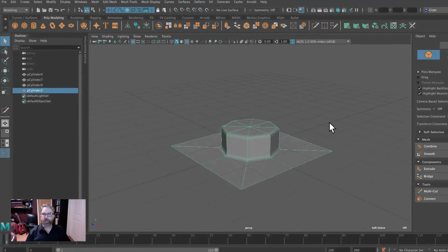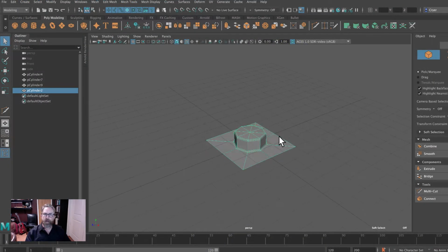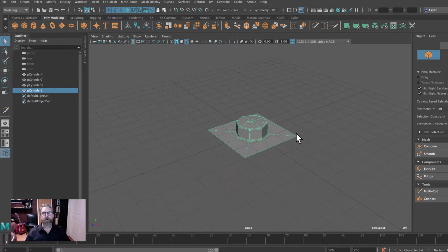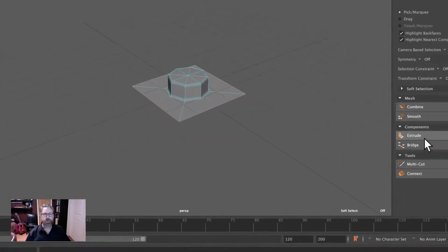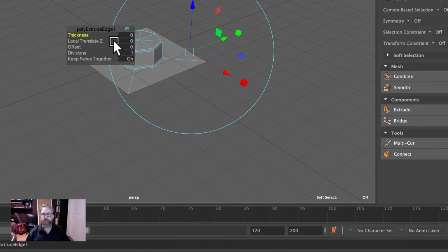Let's get started. We'll begin by building our one by one. You could import your one by one brick start, but just for review, I'm going to build one from our peg start. So if you'd like to follow along, File, Import, Peg Start. We'll double click that outer edge. We'll come to Extrude, and our local Z is -4.8.